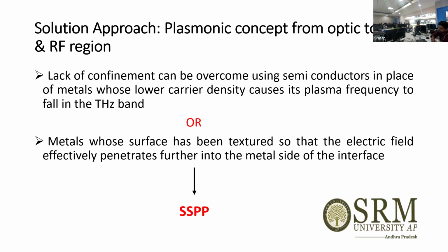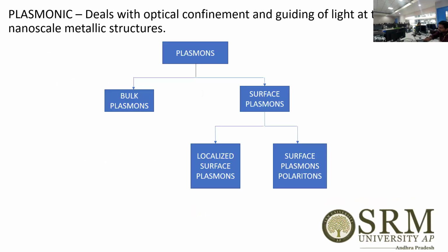By changing the geometrical parameters of the metallic waveguide, we can bring the functionality to the lower frequency range. So that is the beauty of spoof surface plasmon polaritons.